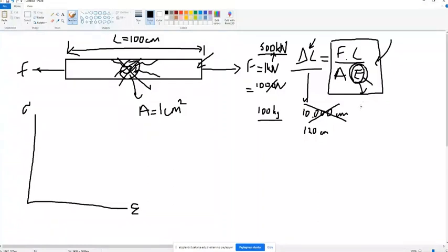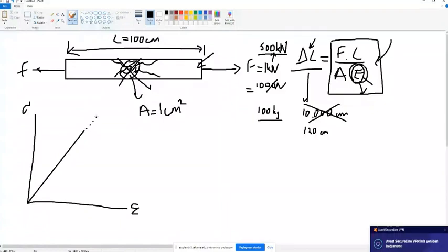It is a stress strain graph, you know. And if you give just the Young modulus, the computer will understand that there is a line, an elastic line, starting from 0, continuing to the eternity. So whatever you have given to the system, the computer will calculate it, but you will get the wrong results maybe.